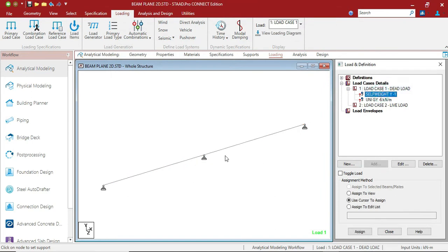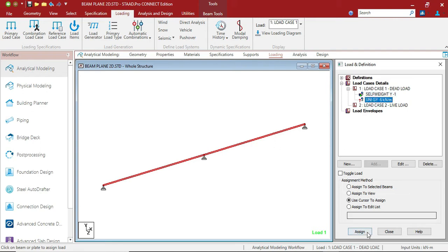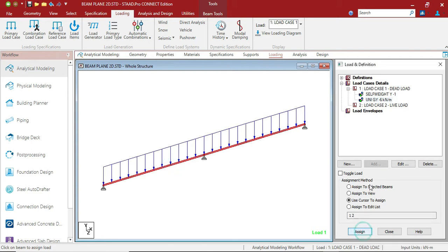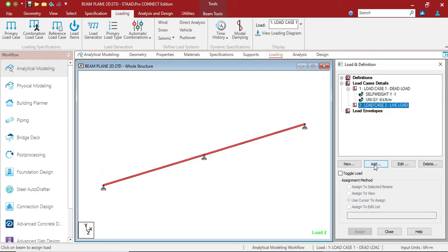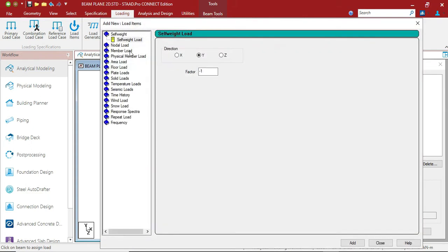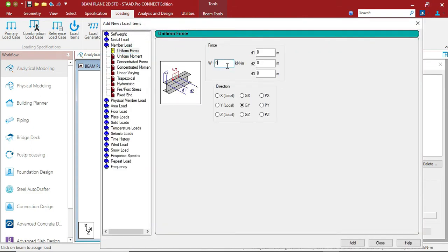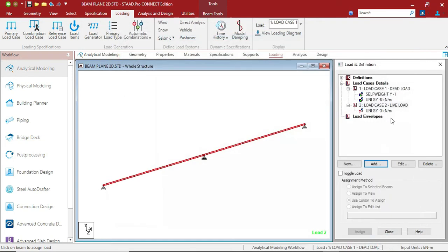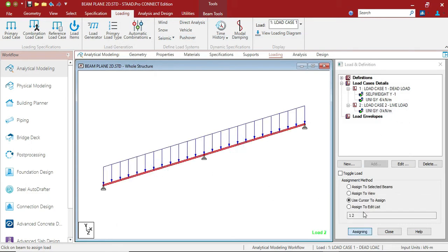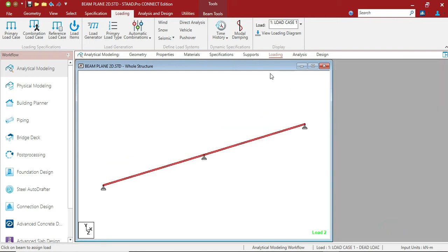After that, we assign all the loads we just chose along the beam. See, this is the image. And then for the live load, which also has a uniform load, the value is -3. Add and close and assign along the beam. Okay, close. After done loading,